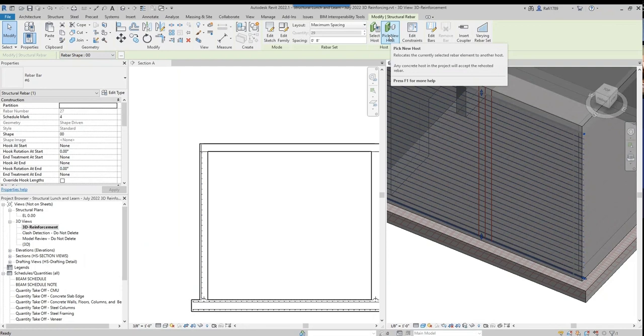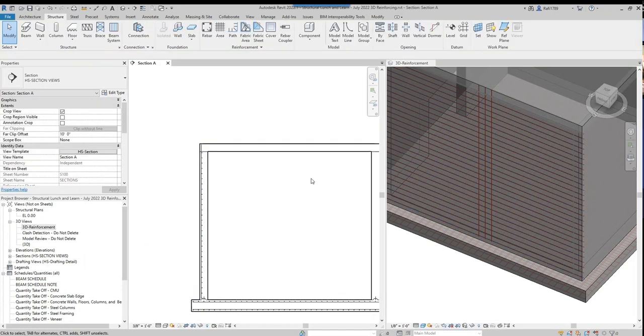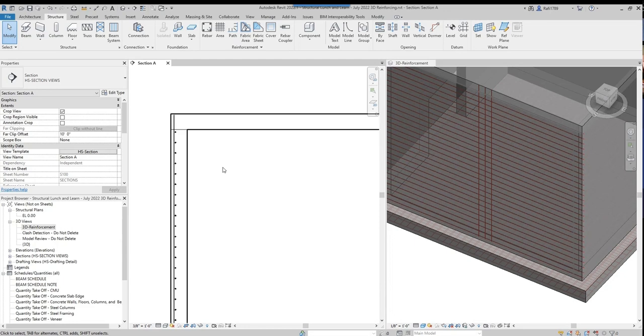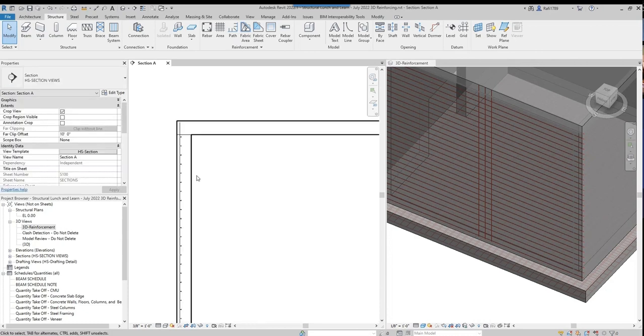You guys with me so far? So these are all little tiny extra steps from just placing the rebar and tagging it. If you have something really, really simple, do you absolutely need to overly constrain everything? Maybe, maybe not. But what this is going to allow you to do is give you so many less headaches as things are changing after you model the reinforcing. And it's also going to make the cleanup way easier, because you're not dealing with rebar that shouldn't be in a particular location. And we'll talk about the things beyond when we get to the rebar cleanup.